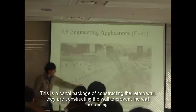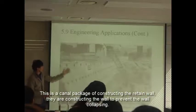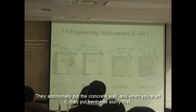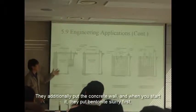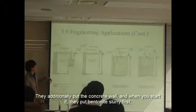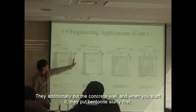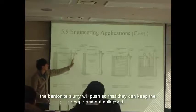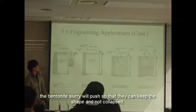They're excavating here and constructing the wall, preventing the side wall from collapsing. With that, they actually put in the concrete wall, which will be the permanent wall for the building. And when you excavate, they put in the bentonite slurry first. This is the ground. So as they excavate, the bentonite slurry will push against it so that it keeps the shape. It will not collapse.